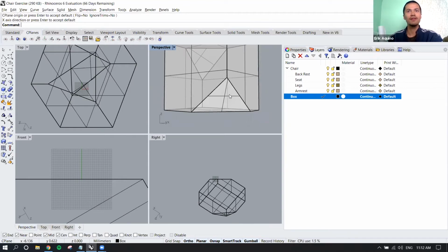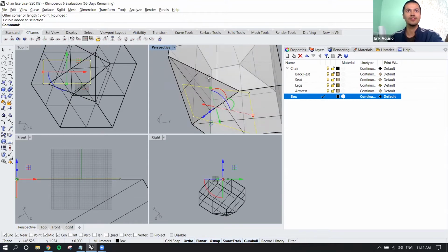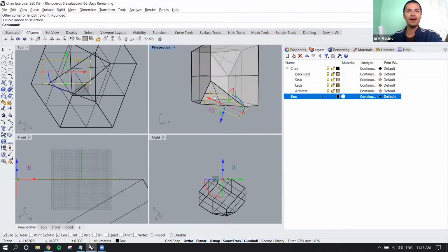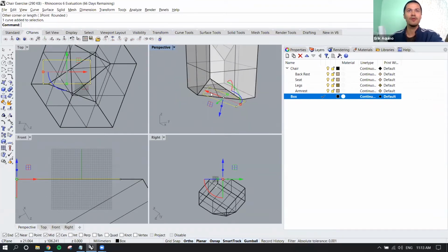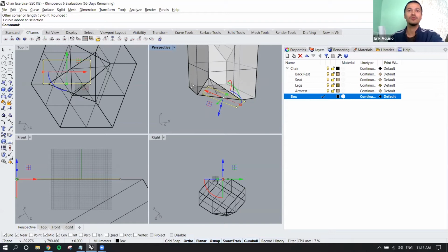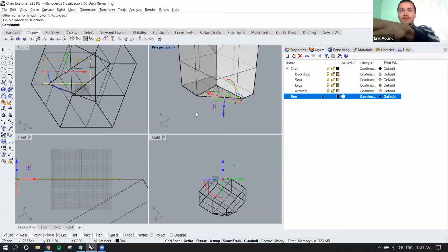All right, so now if I were to create a rectangle, my rectangle is going to adjoin to that plane and lie flat on this surface. If you were to do that same command, applying a rectangle to the surface, when the C-plane is in its default position where X, Y is flat to this bottom portion of the box, then you'd have to do several commands in order to rotate and then move the rectangle to the surface. So that's an easy way to do it.